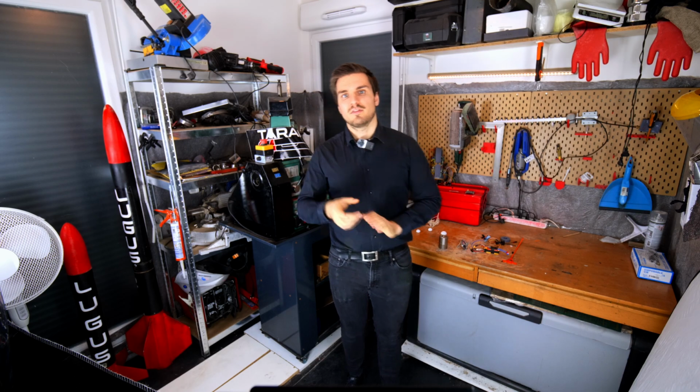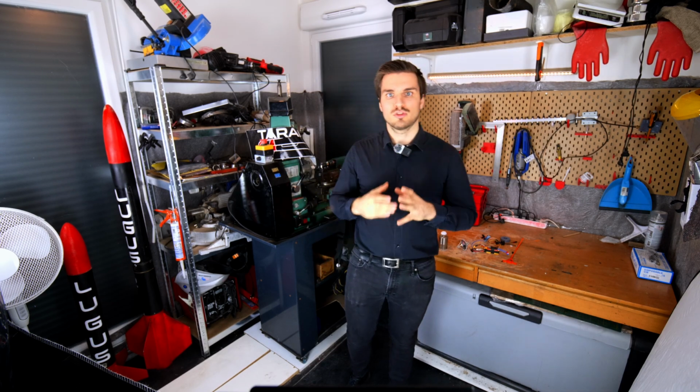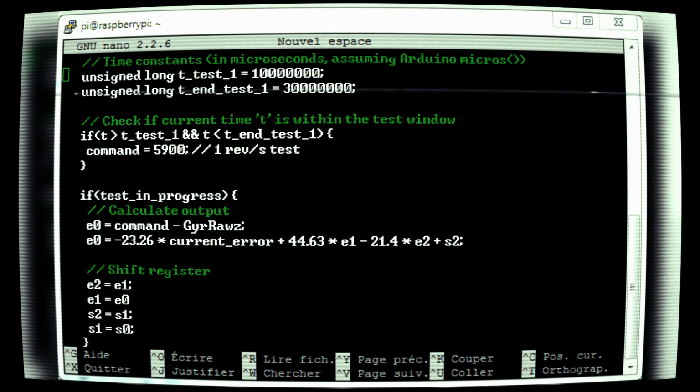Well, first of all, the code I gave you isn't going to work as is. You need to add quite a few things to it. First, if you use the raw sensor data in the system identification tool, you don't need to modify the input of the controller. It is already adapted to what your sensor gave you. So that's something you don't want to modify.